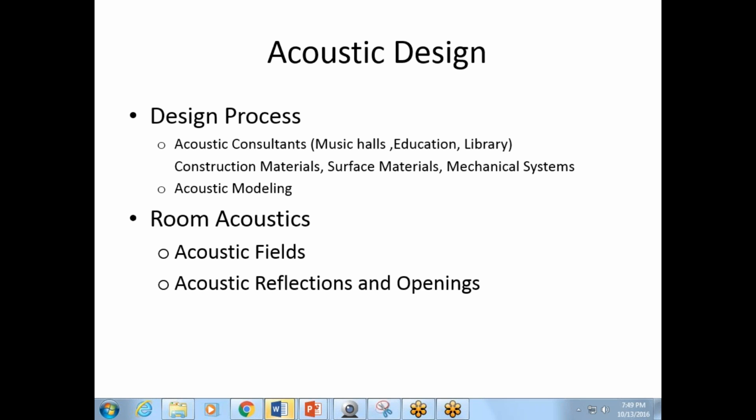Sometimes it adds extra concave surfaces in the ground, which reflect sound in a certain way that's not appealing. But they also have these exposed ceilings. So we have a larger plenum without any room for insulation within the ceiling tile area because they removed the tiles to expose all of the piping. And on top of that, in a bar environment or restaurant family dining experience, this is even worse, I feel, than a bar environment, where we have the two combined. So you have a lot of kid noise, and you have a lot of people who are drinking, making noise in the same spaces next to each other.